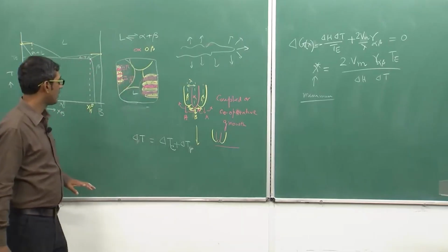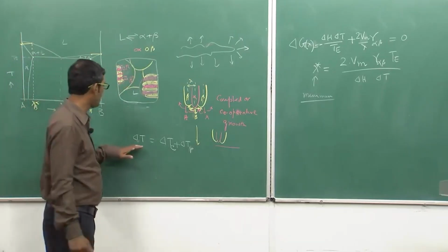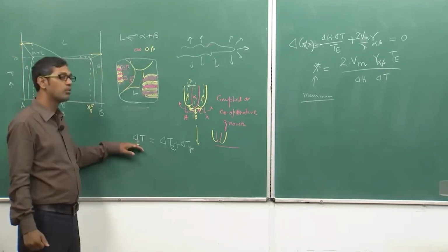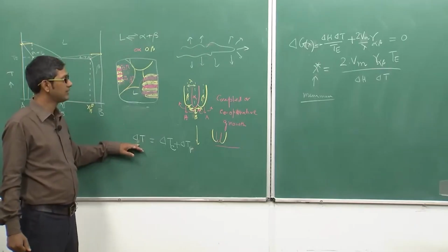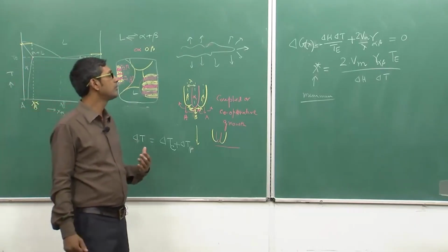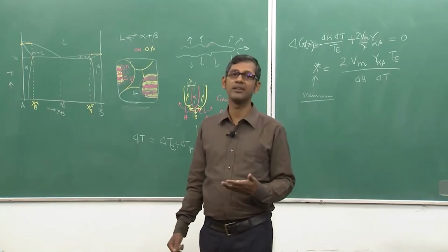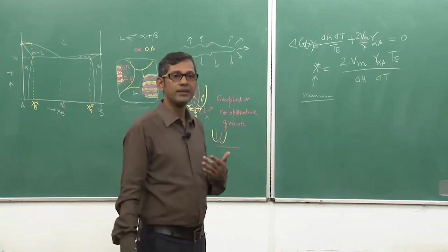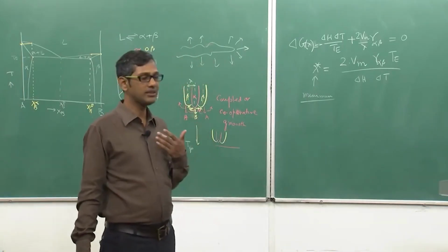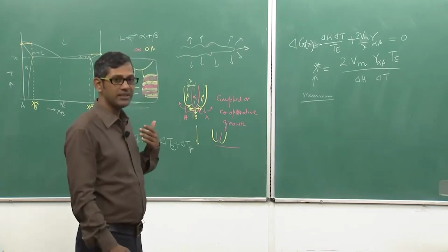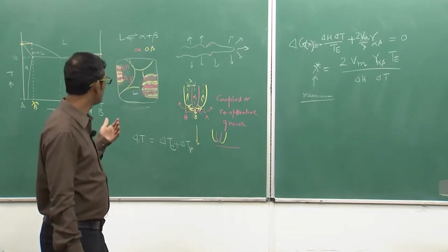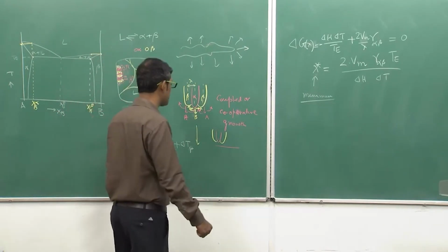In the next lecture we will discuss how I can actually use total undercooling terms to formulate a theory to calculate what is the lambda, what is the velocity of the interface, and how they are related. Just like in dendritic growth, the velocity of the dendrite as well as the tip radius are related by a single equation. So we will also see that it is possible to develop such an equation.